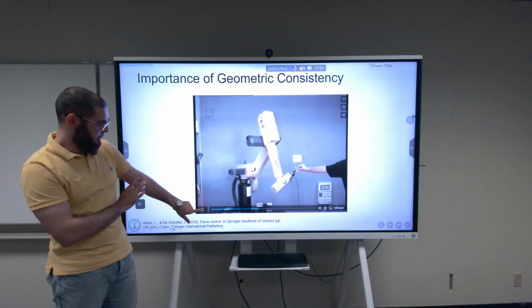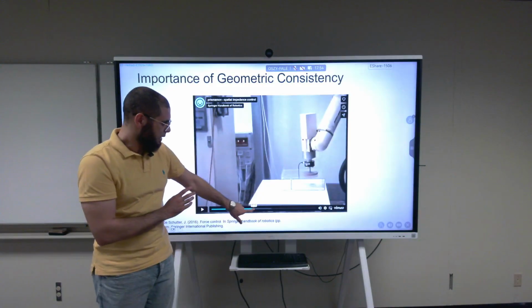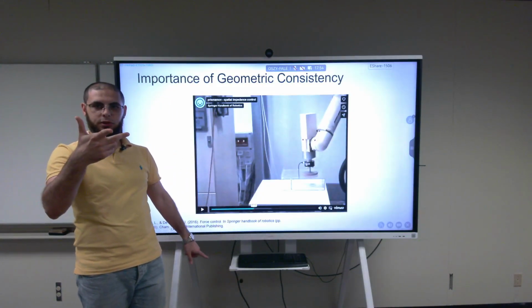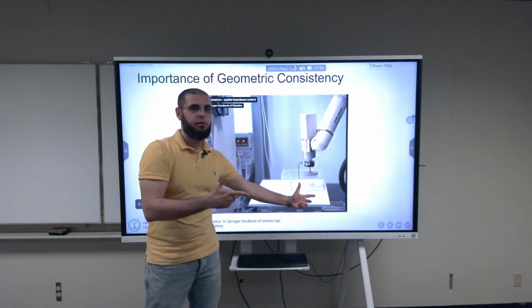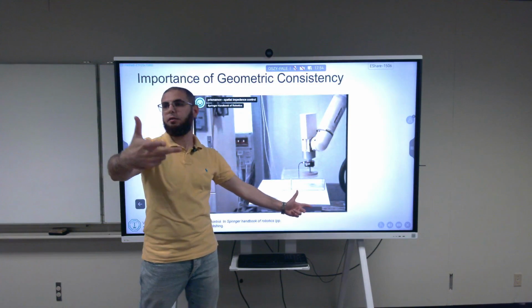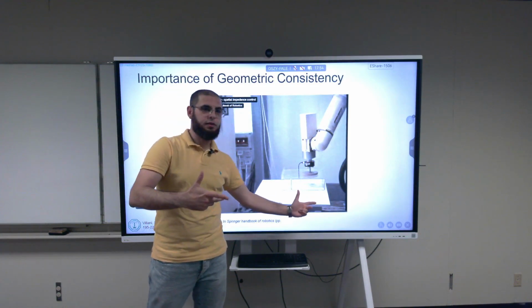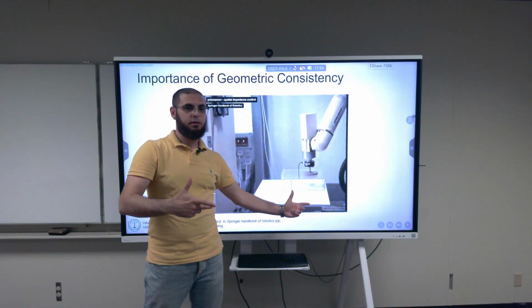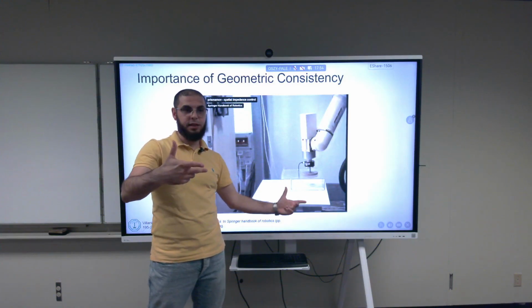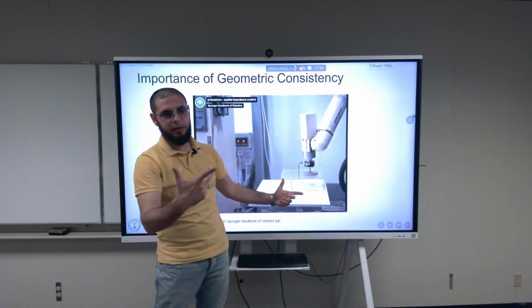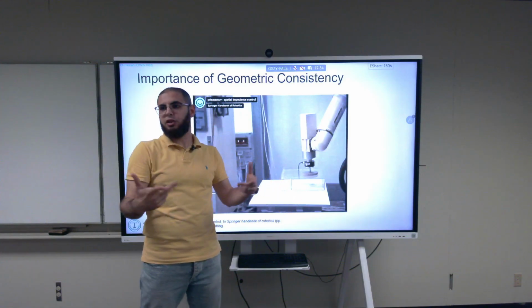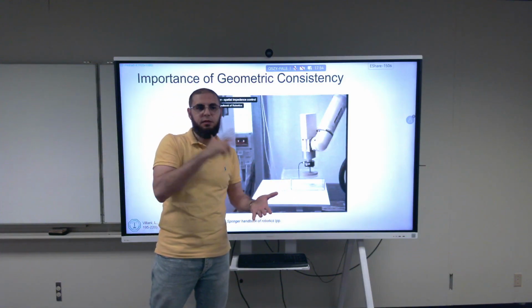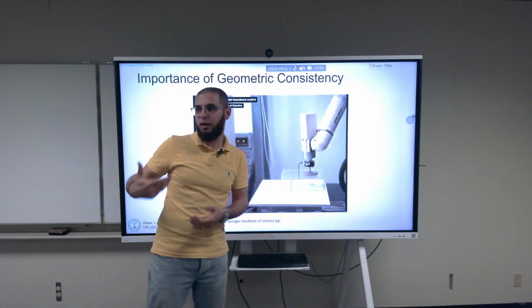What actually happened in the last experiment is that they were commanding the robot to go first up until this point. So the desired path was inside of the surface. It was even with the same orientation, but you see everything was compliant in that direction. It's like the surface is preventing it from having the orientation, so it takes the orientation of the surface. That's the whole idea, right? It's being compliant to the environment.